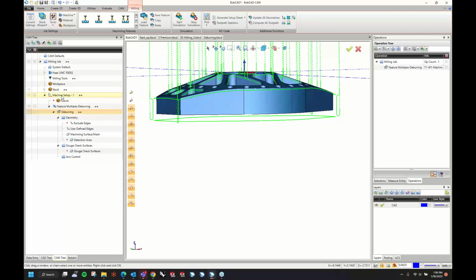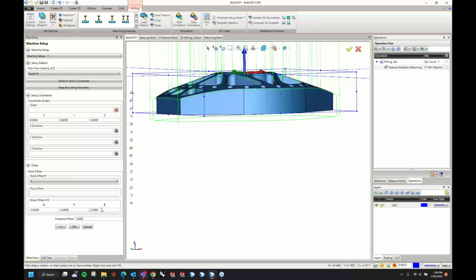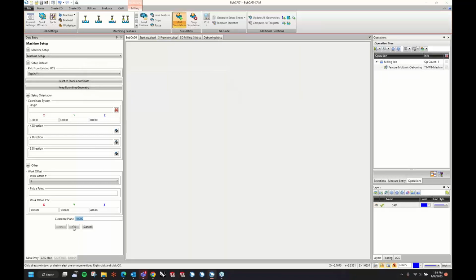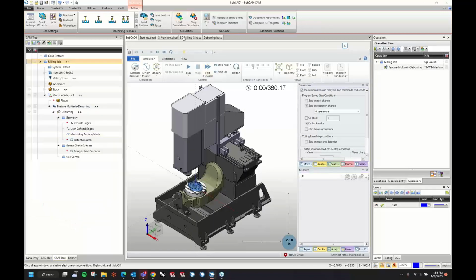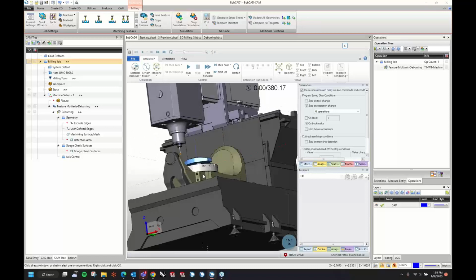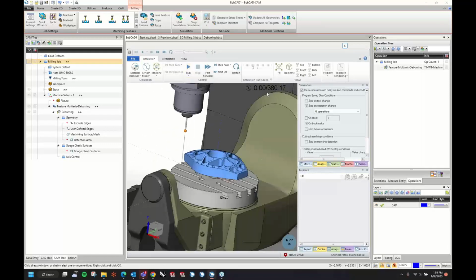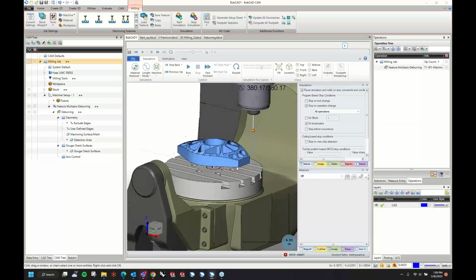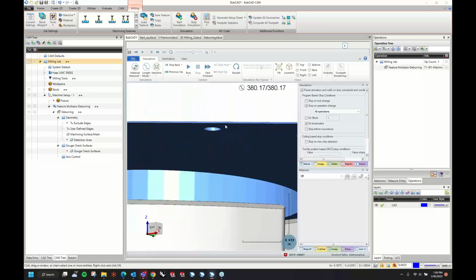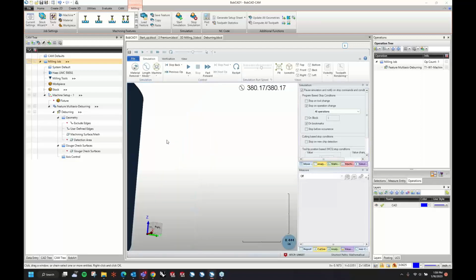It is going a lot lower than where the machine's at, where the tool is. So what I'll do is I'll go and edit this, and I'll make the Z like 4 inches. That'll shift my part up an inch and a half. Oh, I should hit OK here. All right, that reloaded properly and it moved it up. So we'll kind of speed through this one. But I should be able to see a nice little deburr on the bottom all the way around.